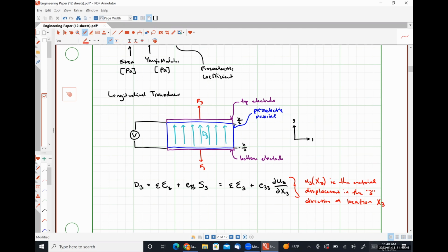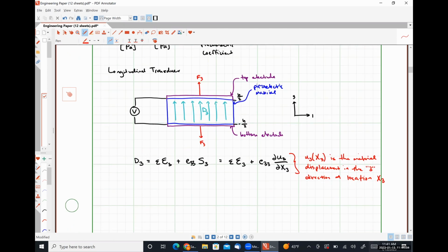So effectively, it's a measure of the deformation of the crystal when we have some induced electric field or displacement field, or vice versa, right? Our piezoelectric coefficient effectively couples our stress-strain relationship to our electric flux density, electric field relationship, so it works both ways. But anyway, so just telling you what the things are as we do the math here.